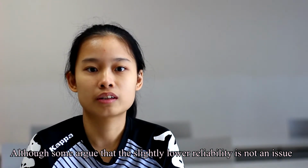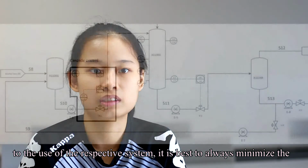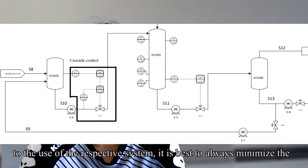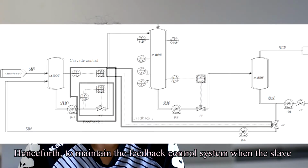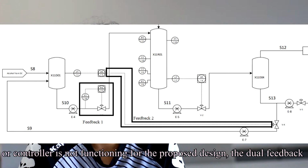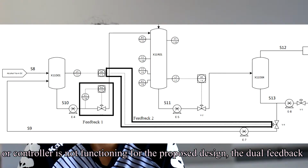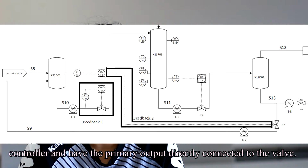Although some argue that the slightly lower reliability is not an issue to the use of the respective system, it is always best to minimize the possibility of error in the process control system. Hence, to maintain the feedback control when the slave sensor or controller is not functioning for the proposed design, the dual feedback control system has the flexibility to bypass the secondary sensor or controller and have the primary output directly connected to the valve.